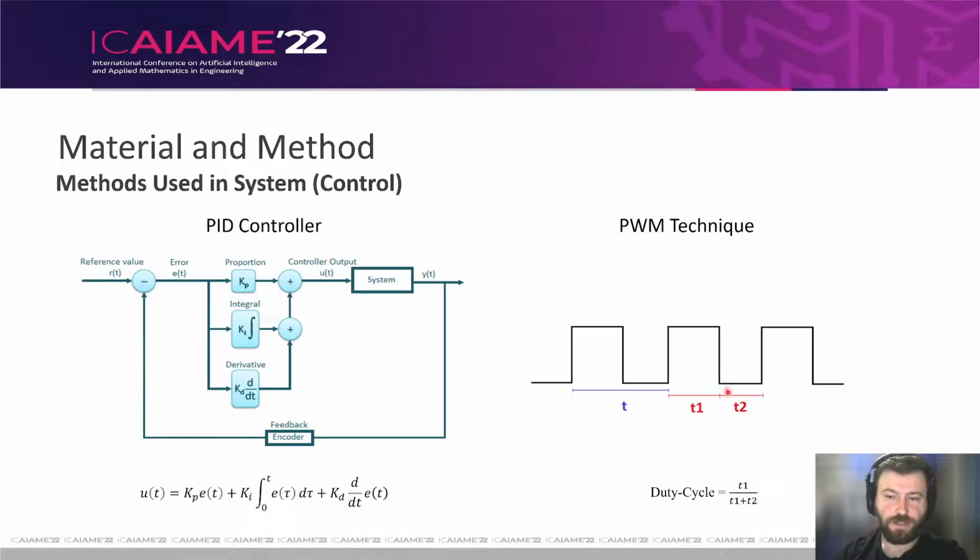As for the algorithm and method that provides speed control of the motor, PID control was used to provide speed control of the DC motor in the project. PID control is a control system that calculates the error value by comparing the input and output quantities of the system in a closed system and generates a new control signal by using the proportional, derivative and integral gain parameters of the system.